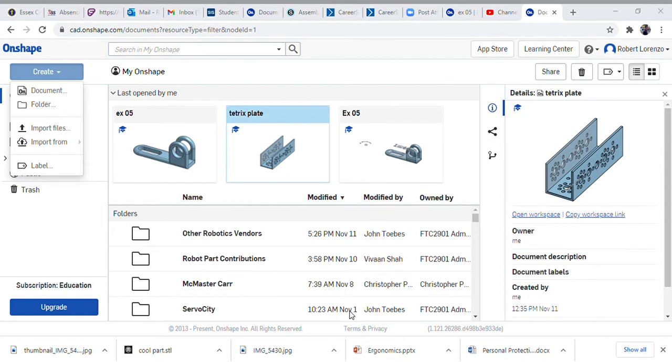So again, coming back, we have 90. That's the center of this hole to the center of this hole. We need to figure out the rest of this distance. So what we see are these arcs. Here's an arc, right? A semicircle we're going to refer to as an arc, and here's a circle here. So we see this circle has a diameter, remember that symbol is the diameter symbol, of 25, and this outer arc has a radius of 25. Remember, this center is the center of both this full circle as well as this arc.